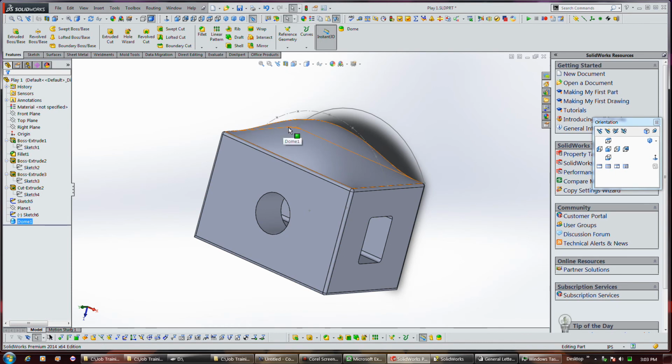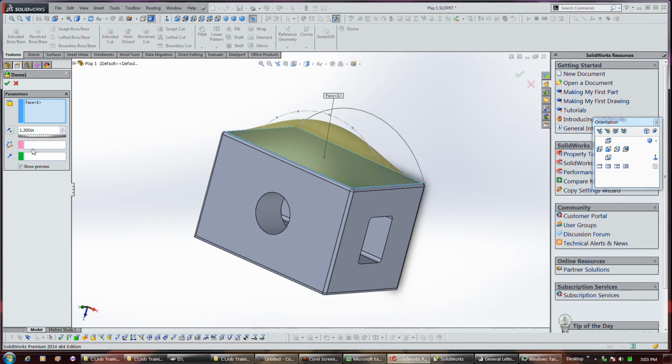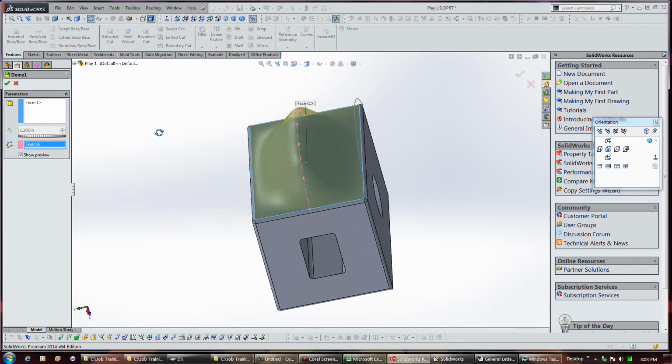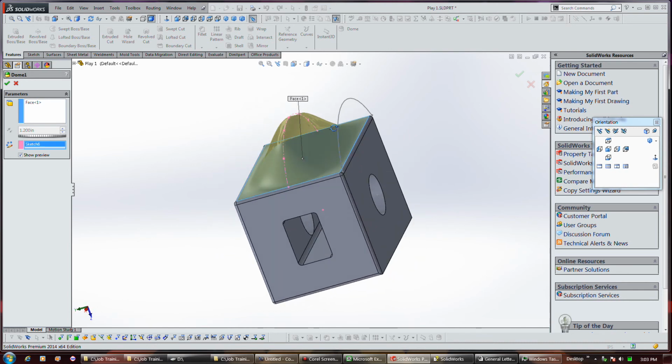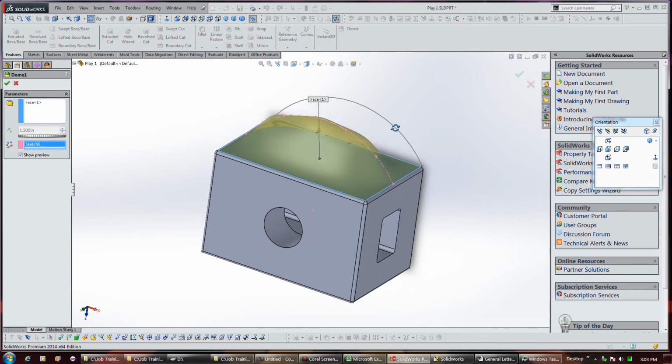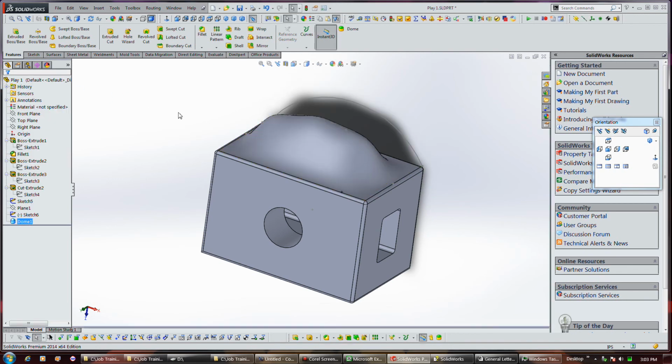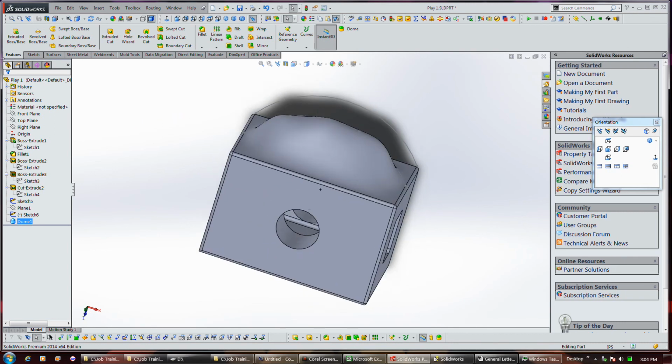And in fact, I'm just going to demonstrate some of the principles. Okay, so if you go select and edit the dome, and I select my sketch, you can see what it's doing. I had to actually go in to edit the sketch and put these points on it, because after reading through the help, it's all based on points apparently. So how these points are spaced determines the shape of the dome in that profile. So that's basically what that does. Or to complete it, it's kind of irregularly shaped.